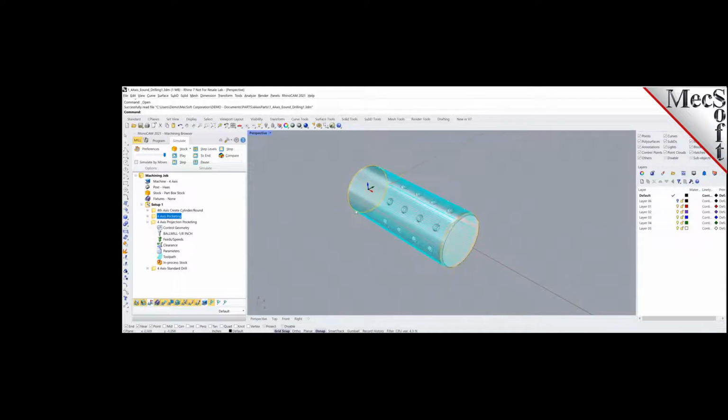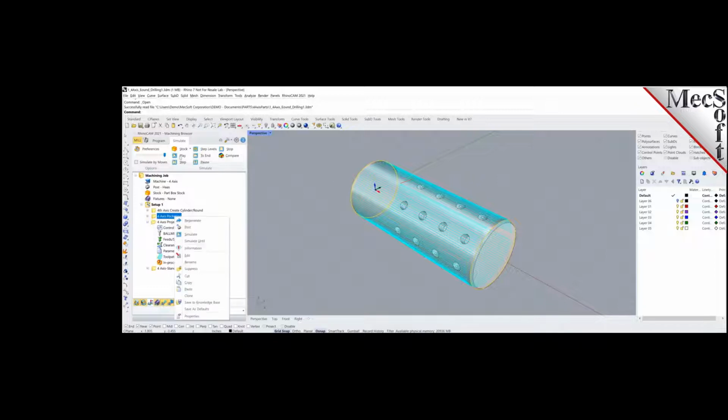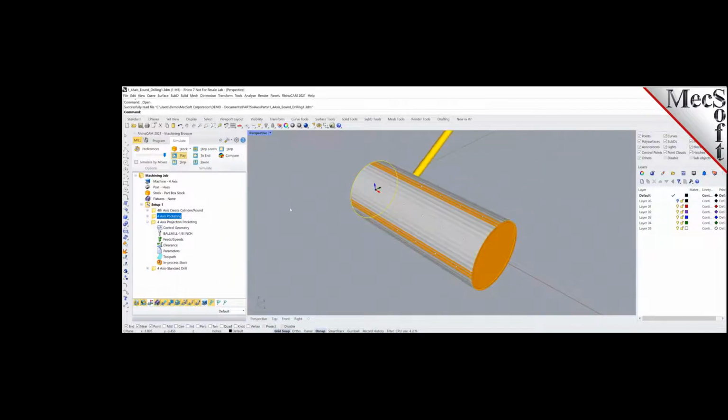And then this is what I call the wrap method. I selected these two curves and did a pocketing method. Basically, internally, we unwrap that into a rectangle and do a pocketing. And so now I'm actually finishing that. If I need to finish, I'm finishing it with the rectangular block. I mean, a rectangular tool rather, a flat tool.